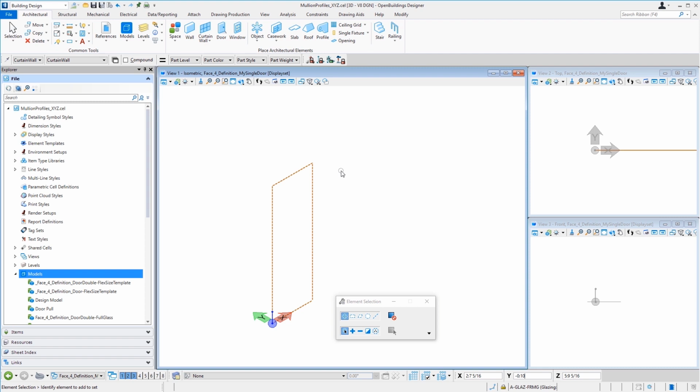I'm also going to add a couple of constraints to this rectangle. Constraint modeling means we build constraints on the geometry so that it behaves in a certain way. So there's a couple of things about this rectangle that we want to make sure happen. For instance, we always need that lower left corner to be at the 0, 0 origin. We don't want to be able to move that rectangle off that origin.